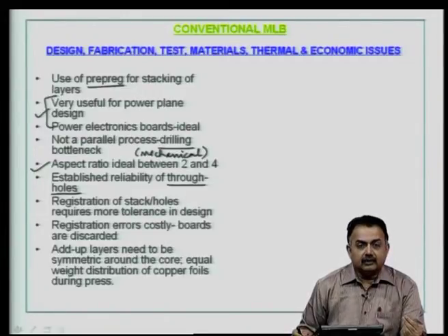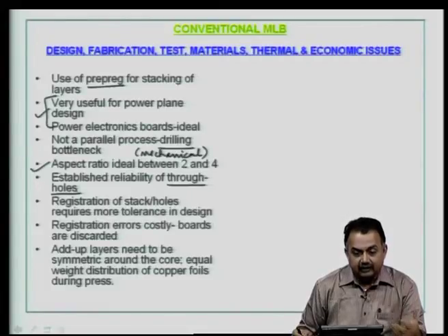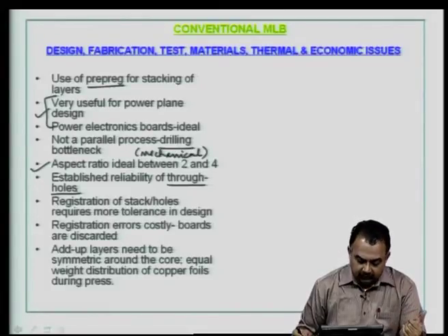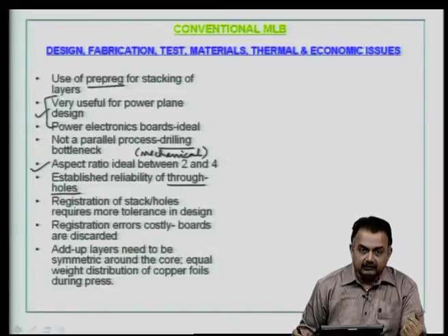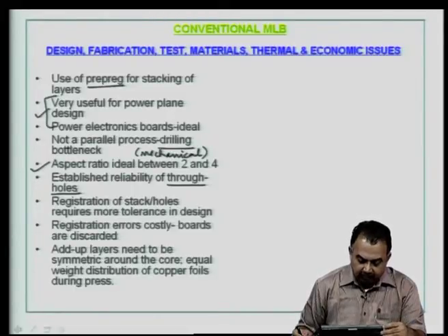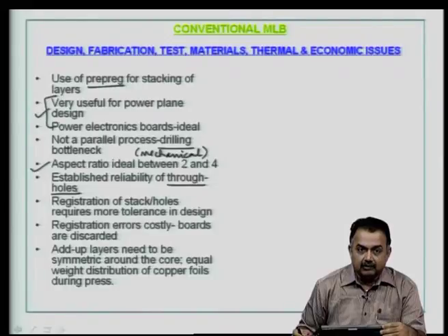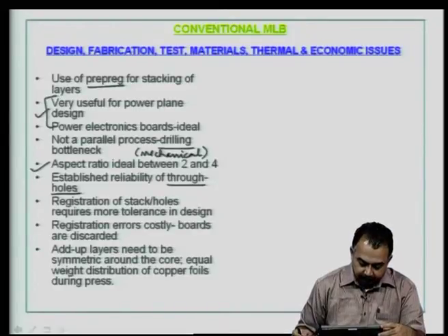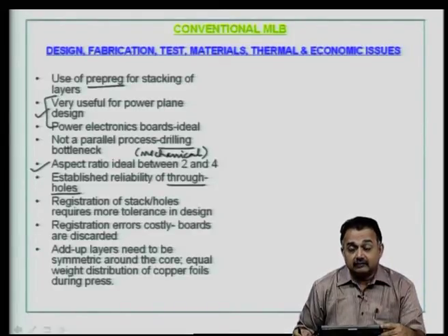The registration of stacked layers and the holes requires more tolerance in design, because as you know there are guidances based on IPC, military etc. in manufacturing as well as in materials. But you have to have a good understanding about the tolerance levels, dimensions, and accordingly you have to incorporate it in your design. Registration errors will be more costly. In some cases boards are discarded.